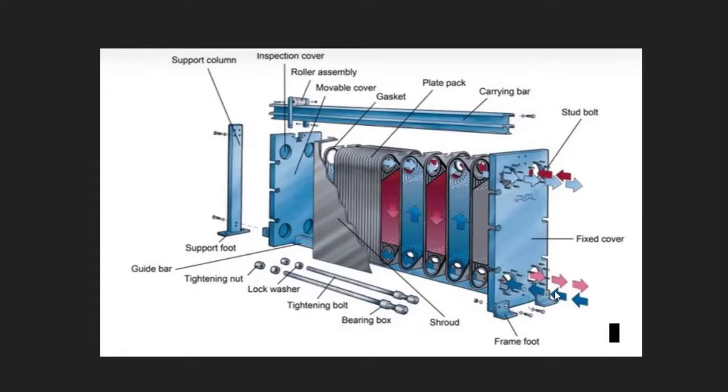These are the feet. The only reason why I mention the feet is because they are a key component of seismic design when needed. As we said earlier, the thickness of the frame depends mainly on the pressure rating, and in some rare cases, the seismic requirements of particular locations. If you see a GPHE with a thick frame with a lot of bolts and nuts, it means that the unit has been designed to withstand high pressure.